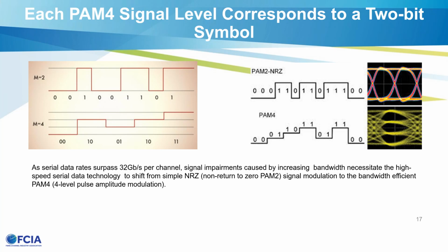And the experts that do this work, there were a lot of trade-offs looking at signal to noise and CDR locking and things like that, to determine what for these particular rates seemed to be the best path forward. And I think you would find when you look at other standards, whether it's IEEE, OIF, et cetera, everybody pretty much, whether it's 50 gig or 64 GFC, made this transition to PAM4 signaling.